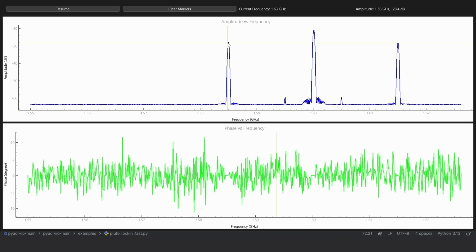Because you are sampling very close to the Nyquist, it may not be able to see all the transition behaviors. So there is some spectral leakage, which will reduce the power that we receive. That is one thing to note.